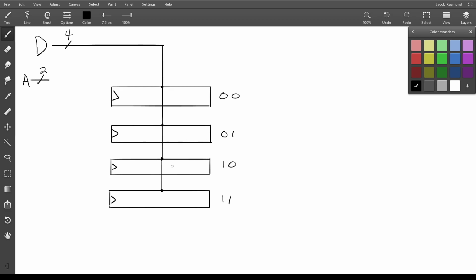And we can then use the clock and only the clock as a method of controlling where we're writing to, right? If we want to write to this one, then all we have to do is set this line to 1. If we want to write to this one, then all we have to do is set this line to 1. And that way, keep the rest of them 0, obviously, because if the rest of them are 0, then all of these will just stay the same.